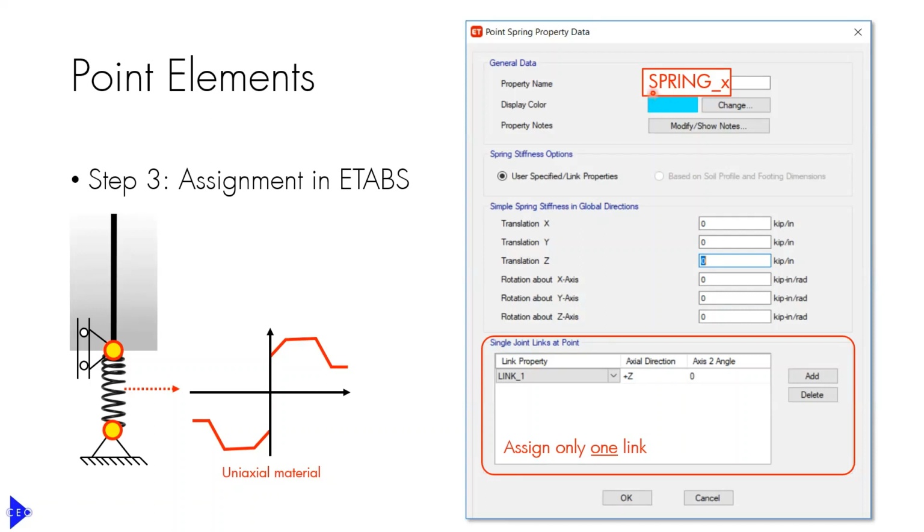And depending on whether you're using spring, hinge, or joint, which are the three flags, OpenSees will either create a support spring, an internal hinge, or a beam column joint. You've got to be careful when you're working with these, because the different flags, spring versus hinge versus joint, will create different types of elements and different types of boundary conditions. But it's all kind of automated.